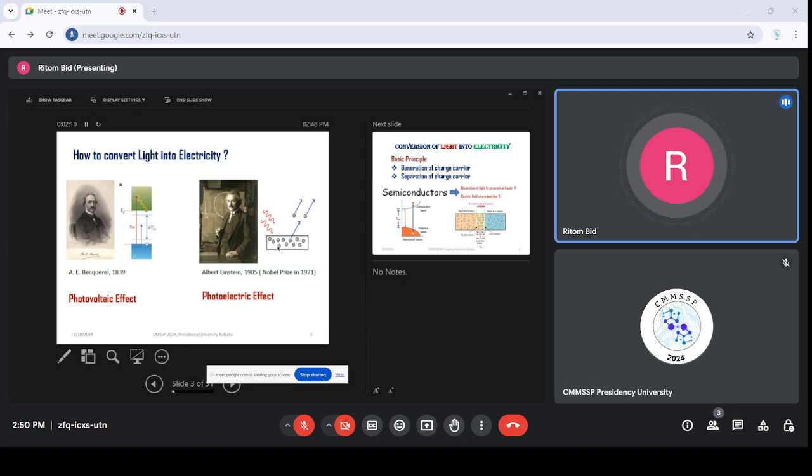They're not going outside the material, right? For the photoelectric effect, we are getting the electrons ejected from the material, right? So if you want to get an electric current out of that, you have to make another arrangement like a photomultiplier. You know about it. But for the photovoltaic effect, you get the electron-hole pair. That is the concept, the creation of holes, and that is the bottom line of the photovoltaic effect.